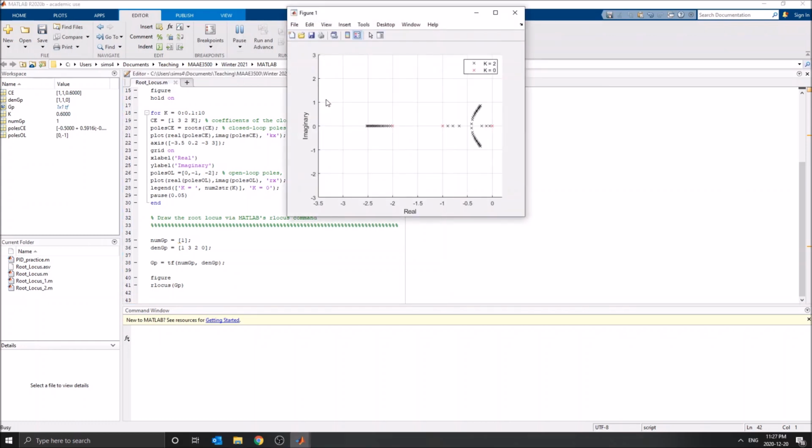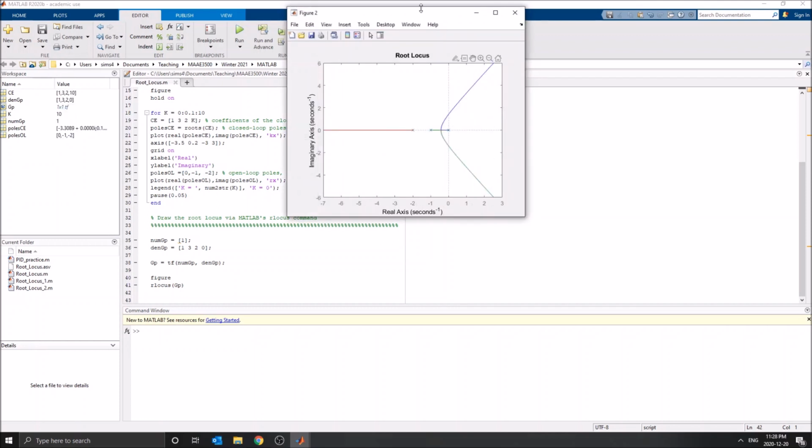So now you see that as you increase your static gain k, the poles smash into each other here and will eventually cross the imaginary axis at some values, while this pole just flies off to the left. Exactly as we've established manually when we had done this example together.